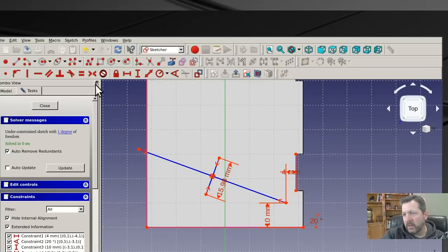Instead, I'm going to use the polyline tool, and I'll draw the first line, and then pressing the M key cycles through magic mode, and the first click makes the line perpendicular, so I'll just repeatedly press the M key and draw the next line, and I'll end up with a rectangle. And in fact, by clicking on my line, I've already constrained the base points to it. Let me do that one more time for the other slot.